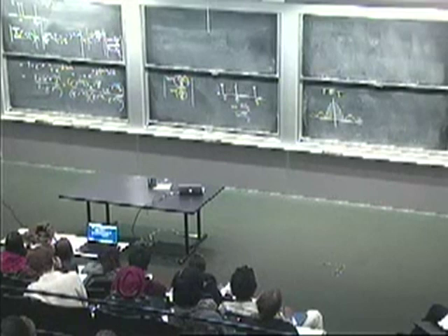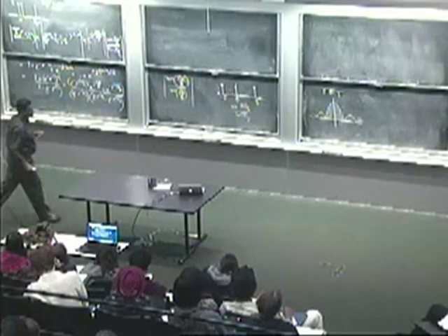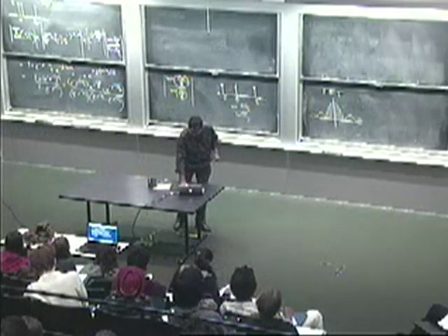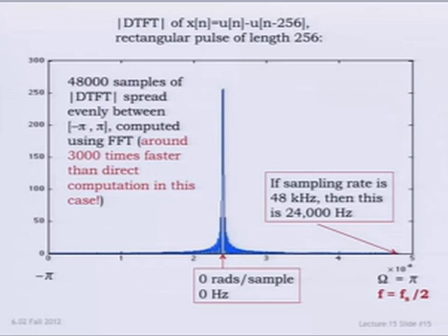If your samples came from sampling at 48 kilohertz, for instance, then the rightmost end that corresponds to pi in terms of actual frequency would correspond to the sampling frequency divided by 2, so that's 24 kilohertz sitting there. So I actually have 24,000 points for 24,000 hertz. So I've got 1 point at every hertz position, but I could pick anything else. The other thing I wanted to mention was that the reason I could do this is because I'm using the FFT.